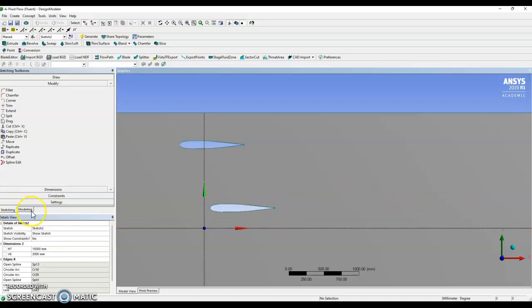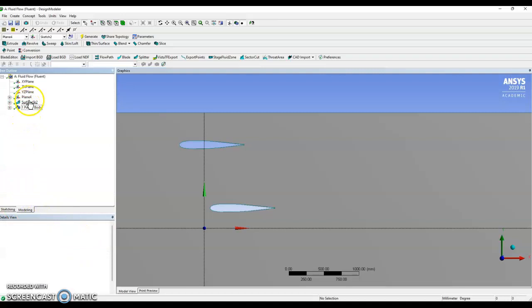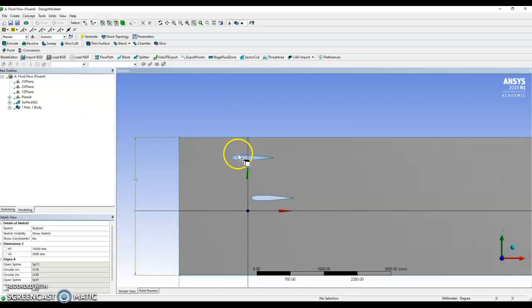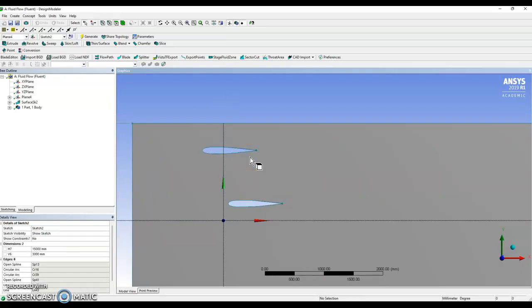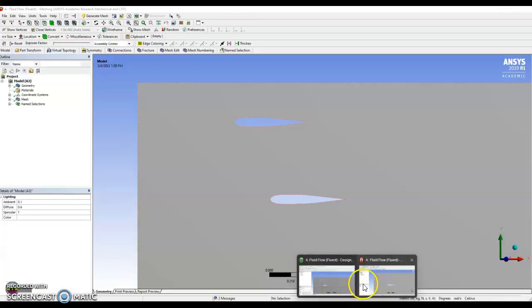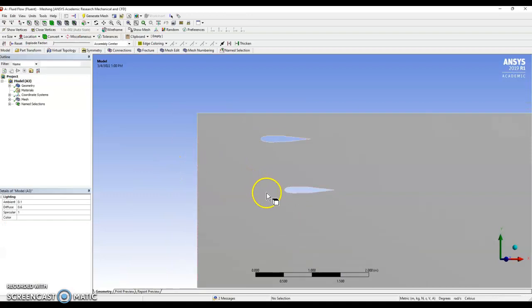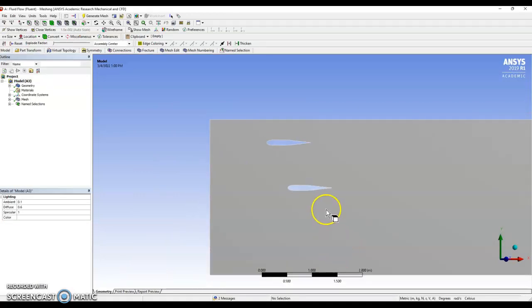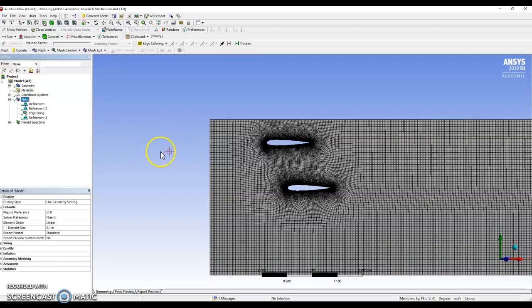Once this has been done, you can then take a surface from sketch, and then add these as your part body, and then it would create what we have here. And this here is an aerofoil configuration. No, two aerofoils in an environment which is now ready for meshing, which I have saved here. So using this, now when you've brought it into this tool, personally, my preference is to straight away mesh. However, this is a complete model. This is not what it would look like at the start.